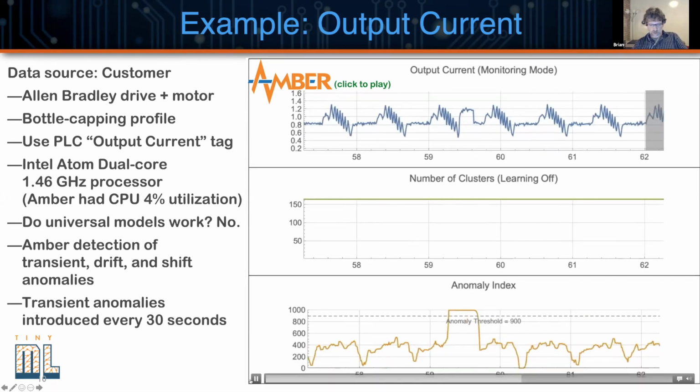And let me just make a comment about this here. So we take a look at this signal. This is a small sub-signal. If you're trying to detect this type of deviation based on threshold, you would not detect it. It's very difficult to detect. And actually, FFT-based detection of this type of transient anomaly is also extremely difficult because of the windowing that's done with the spectral analysis. We do use FFTs in some applications. We can use it, but this is being done on the raw time domain signal.